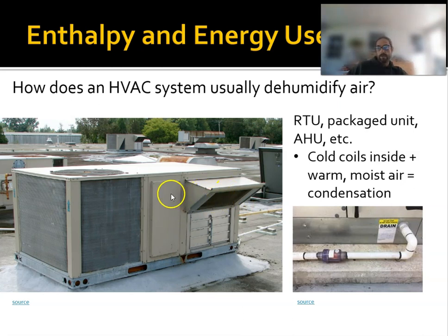If you don't need any fresh air, you can just circulate the indoor air through this system, and these can close off depending on the type of system you have. We dump heat out here, and then here we absorb heat from the air around it, because in order to vaporize, we need to absorb heat, which cools down the air. Then there's ductwork and an air handler that blows cold air down.